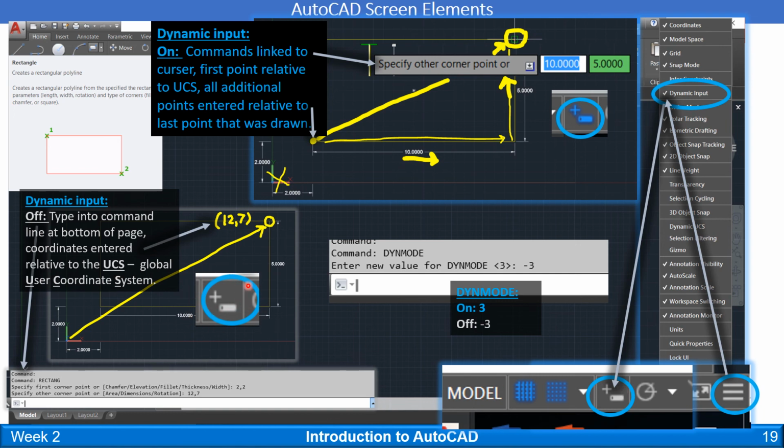So here's the situation where it's off, okay? If it's off, all of the coordinates you enter are going to be relative to your user coordinate system, so your UCS. So the first corner here would be at 2, 2. So I'm going over 2 and up 2 from my user coordinate system. And then with the dynamic mode off, my second coordinate is also going to be relative to my coordinate system. So I'm going to go 2 plus 10, 12, or I'm going to do 2 plus 5, 7. So instead of just going over 10 and up 5, I'm still entering coordinates relative to that original coordinate system.